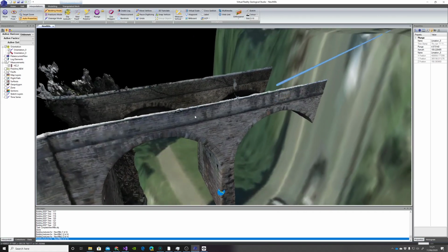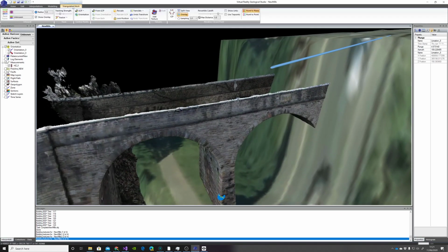So my next step here is back to the extended mesh menu, and from control point select orientation, where you can plot or draw on a vector, and then we say we want this to be dipping at 4.5 degrees towards 159.2.